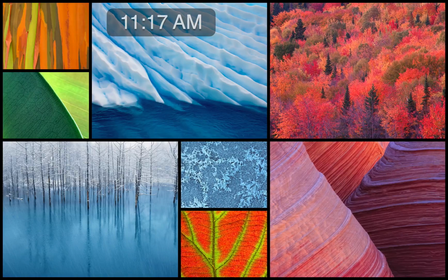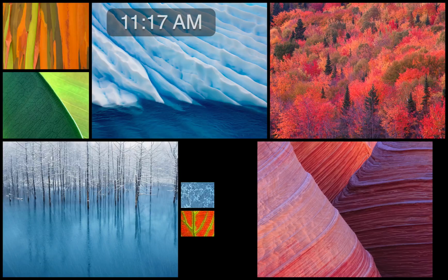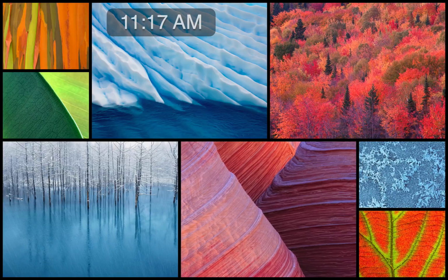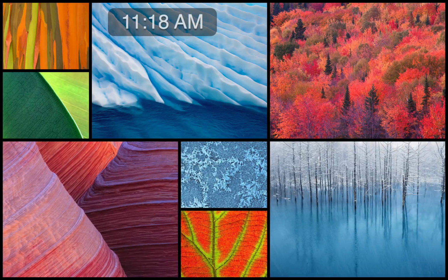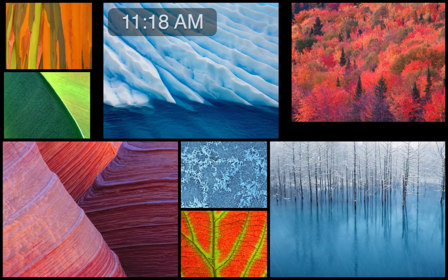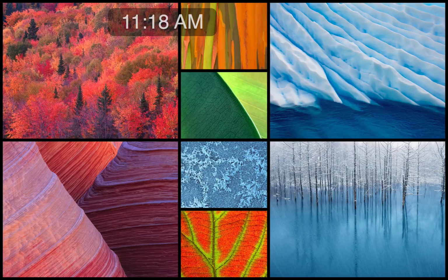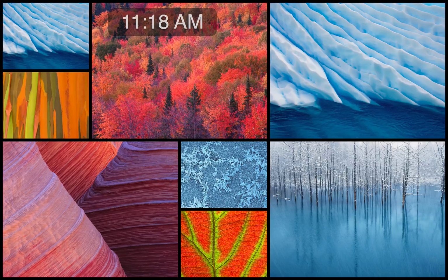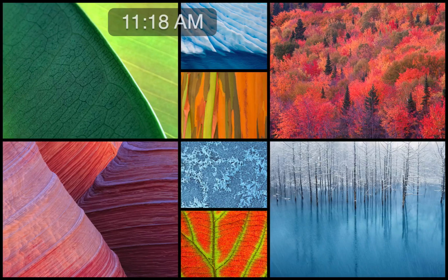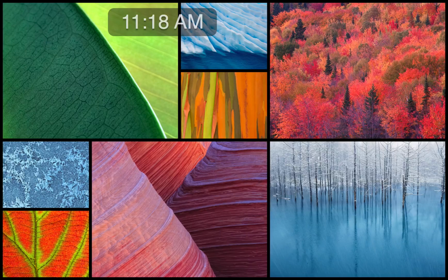Cannot load it. All right, we're just going to fake it, and this is very unfortunate because the whole benefit of using the correct one is we can get the right density and the weight. So let's just, for now, so we can move on, choose 2x4, and then hit Edit Type, and then we'll just duplicate this and make it a 4x4. So I just changed the dimensions to be 4x4.